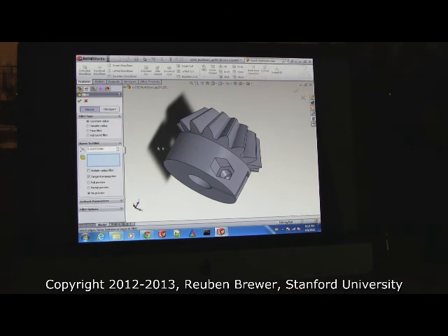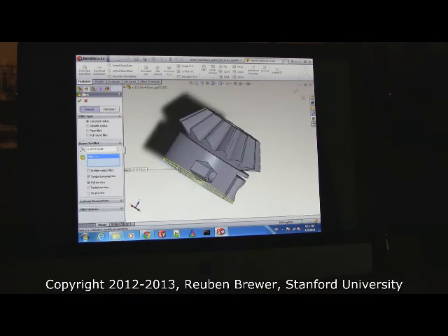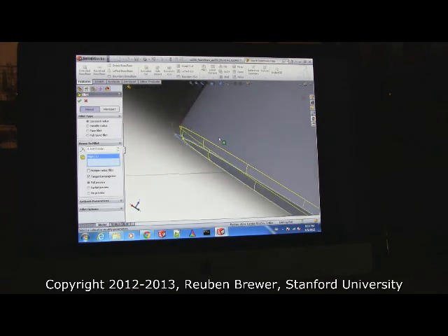And now we're going to start clicking stuff wildly. Okay, watch this. Watch my screen. I click the edge. This time we're not clicking surfaces, we're clicking edges. If it doesn't show you, hit full preview and it will turn yellow. See that? No preview doesn't show anything. Full preview shows what it will look like. So it's just going to take that corner off by rounding it.